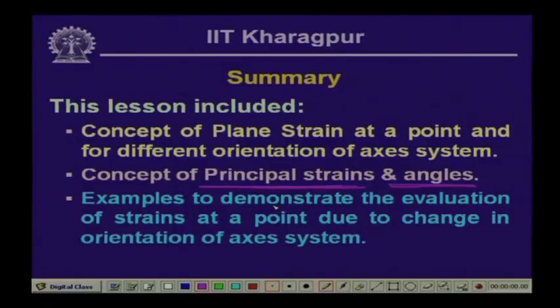Also, I have set one problem for you in which we got to compute the value of the strain with reference to the rectangular axis system in an axis which is oriented at an angle of 30 degree with x in an anticlockwise form. So, you got to evaluate that, which we will be discussing next time. So that we know how to compute the stresses with reference to that change of orientation of the axis system.